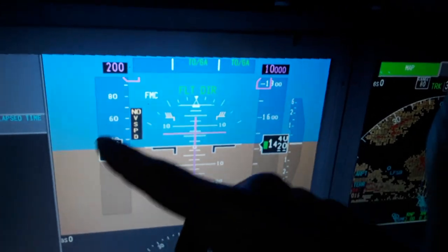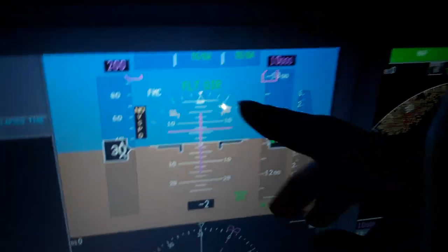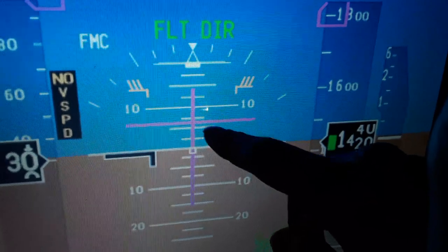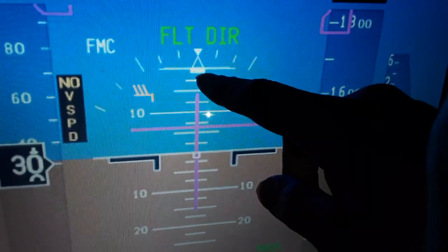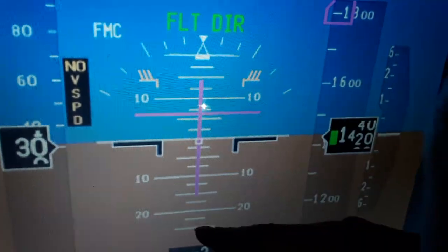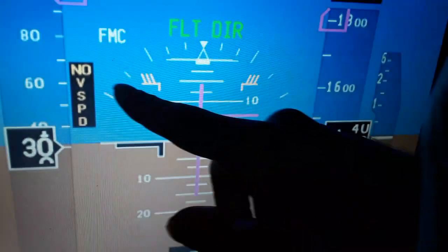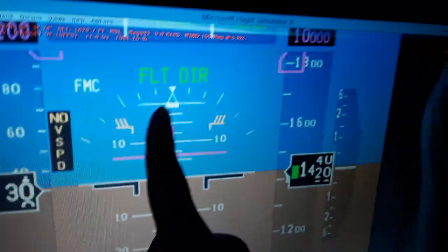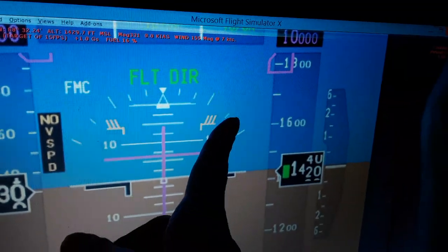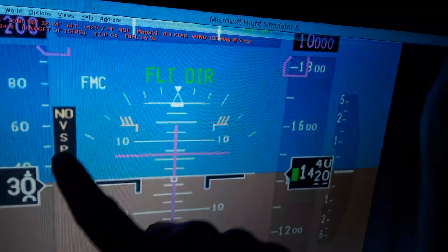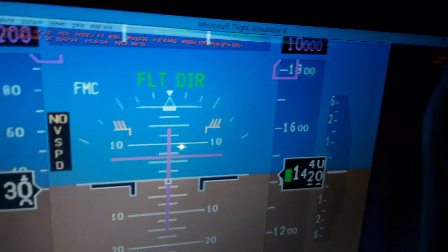We have to pay attention also to the airspeed all the time. The pitch ladder here, you can see 2.5, 5, 7.5, 10, 12.5, 15, 17.5, 20 degrees for pitch up and pitch down. The wings level here of the aircraft when flying, also the bank roll. You can see like 5, 10, 20, 30, 45, 60 degrees for bank roll either left and right.